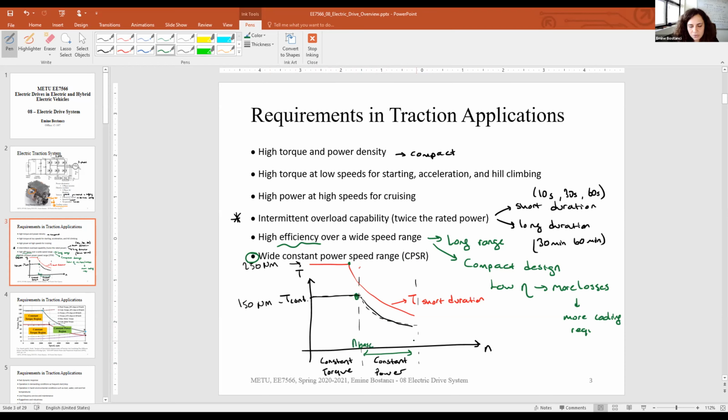And if we can get it in the range of 4, actually it is a good design. So the reason why we want to get 4 or 5 is because we want to have a high torque at low speeds for the acceleration, but we don't want to have this high torque for a long time. So if we have it for a while, then it will be enough. But if we want this curve to continue, this will be good because this is related to our maximum speed.